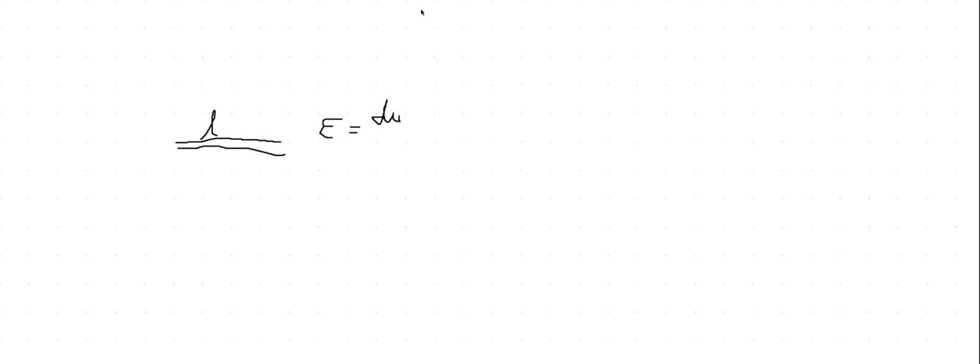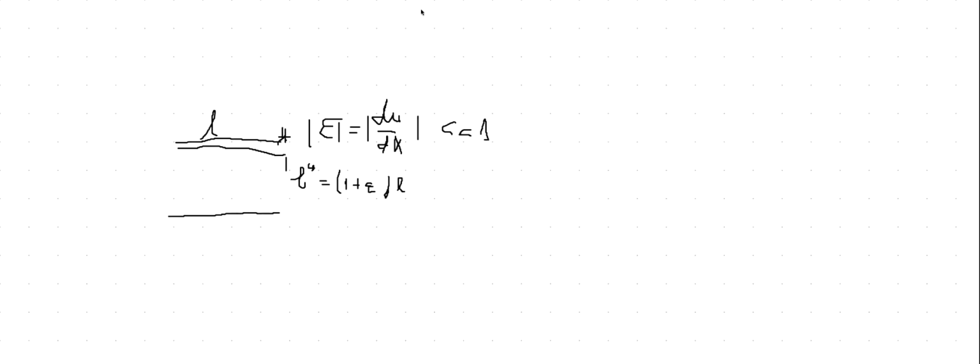and you're just fine. If you want a small displacement gradient theory, the absolute value of this has to be much smaller than 1. But this is the 1D case. When we study large deformation, L phi is equal to, if it's homogeneous, 1 plus epsilon times L, which is almost the same as L.